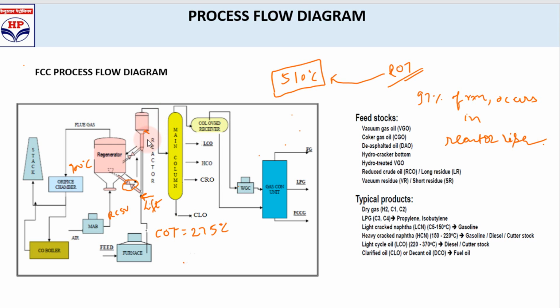The rest, the carbon temporarily deposited on the catalyst, goes to the regenerator, and it is maintained with the level. Suppose we maintain this reactor level at 40%. Based on this, the spent catalyst slide valve will open. This circulation will happen continuously. So the catalyst comes here, then the temporarily deposited carbon burns off in the regenerator, where we give air from the main air blower.